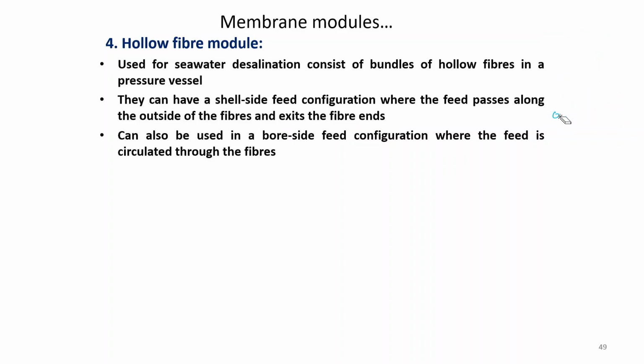So, this can also be used as bore side feed. We can also feed from the bore side, and the permeates are collected from the surface, where the feed is circulated through the fiber. So, here the feed is circulated through the fiber towards the outside. So, both the systems are in use.